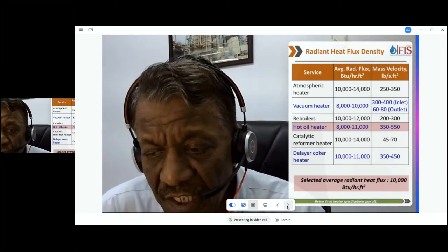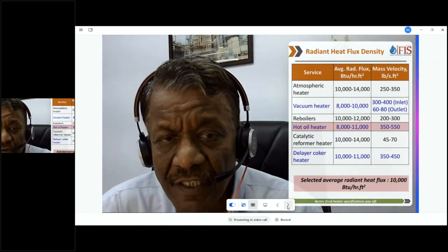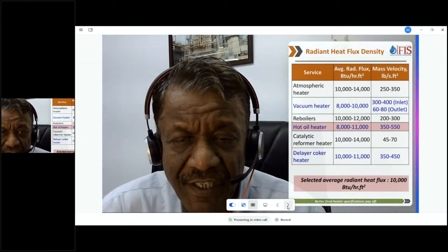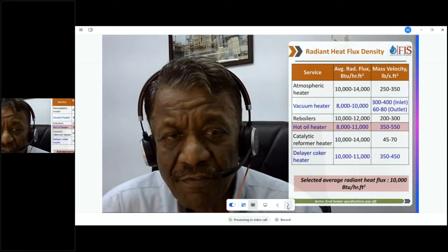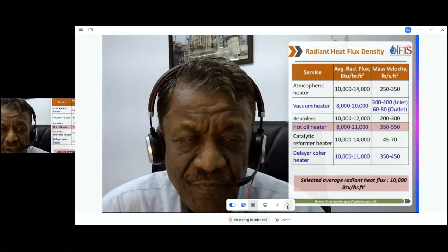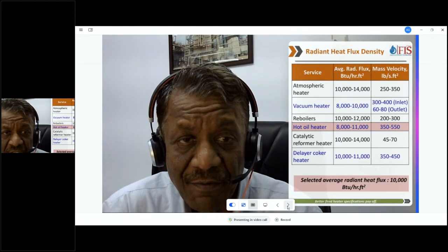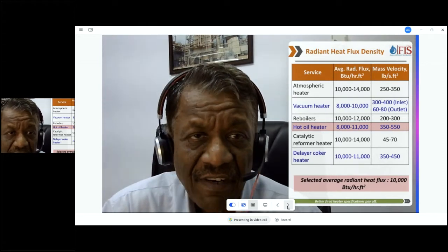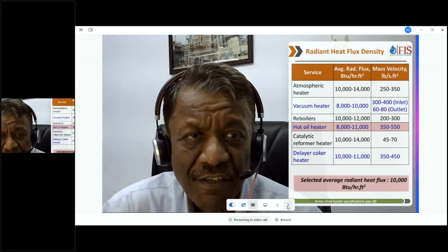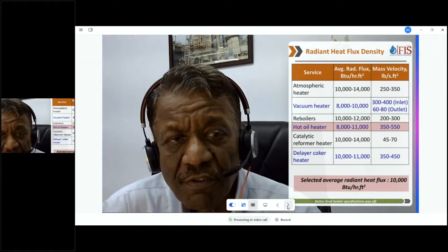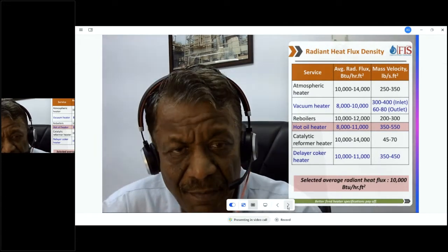If you don't know the flux you want to go with, just use a number which is very, very safe, 10,000. Most of the time, if you go with 10,000 flux, you won't go wrong. If you have a special heater, then it's different, but 10,000 flux is a pretty decent number for most of the refinery services. The other thing you want to specify is the mass velocity, and we have some guidelines over here.